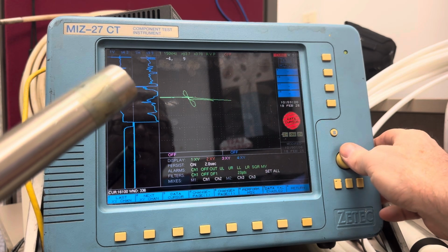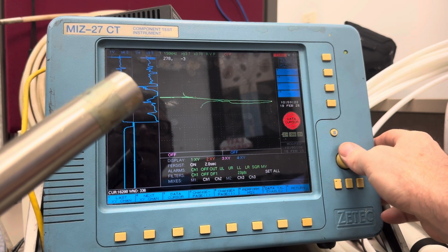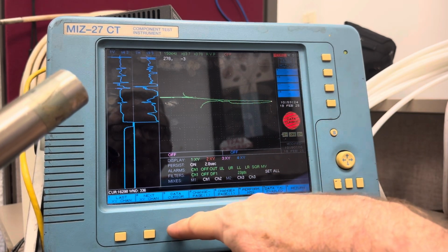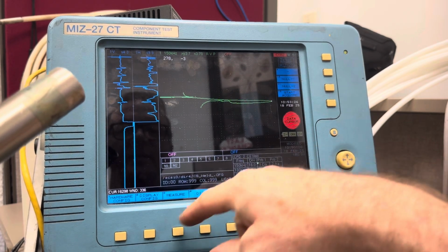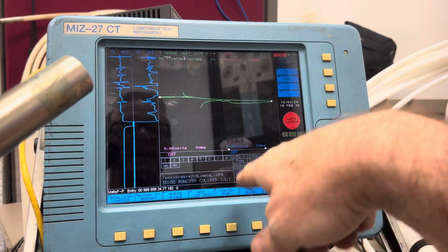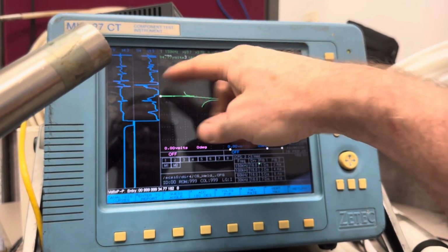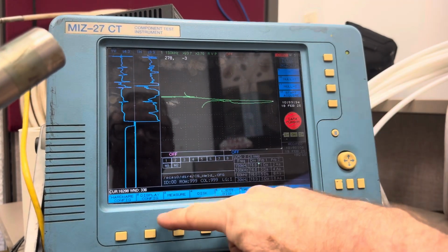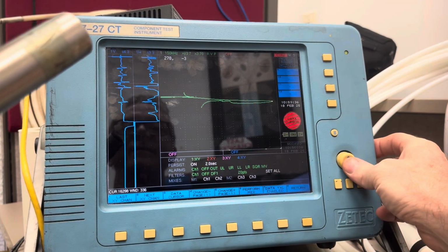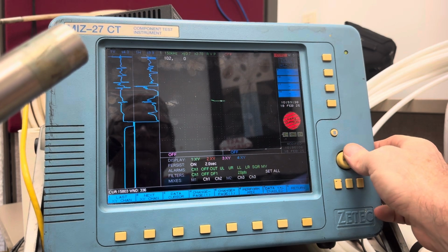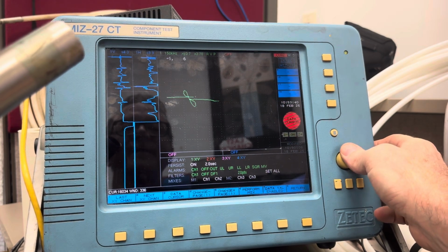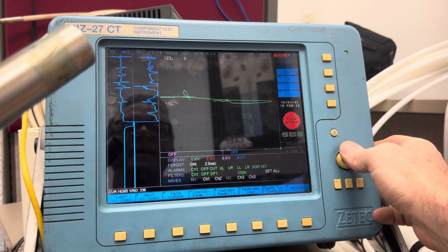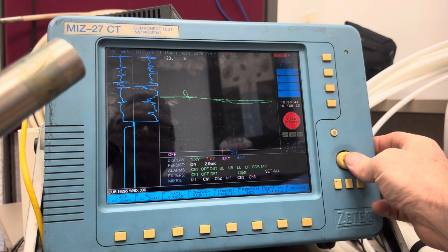So again, I'm going to get just on the dent, and it's right there. So let me measure it and see what it comes up with. I'm going to go peak to peak. It's going to be 182 degrees. That's flat. So as I scroll up into this data, it's going to form to the left first on differential. So goes to the left, goes to the right, and then it comes back to null right there.